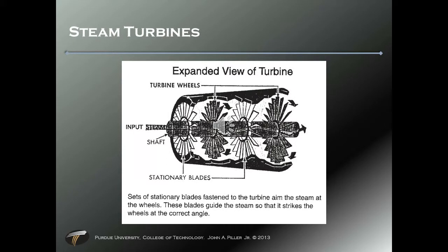So first it reduces pressure and increases the volume. With that we have to increase the diameter, hence the conical shape. And increased diameter means we have to increase the diameter and the length of the blades. The combined sections direct the high velocity steam to create rotation. They're all slightly offset to cause turbulence in the steam to make the push happen.